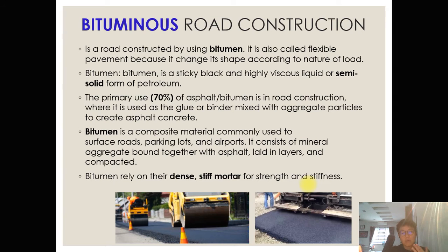So in a small construction or small repair works, they usually just push a trolley with a tank on it, and the fire burning at the bottom. It is a very primitive thing, and they push it along and just pour or scoop it out and put it, and then they'll need to do compaction. Alright, and it's only when the bitumen is set and hardened that the strength and stiffness will be obtained. Alright.